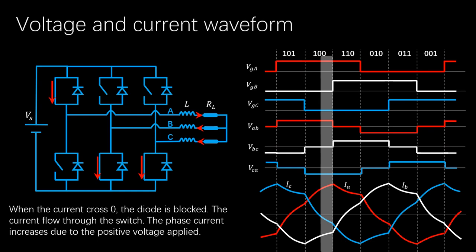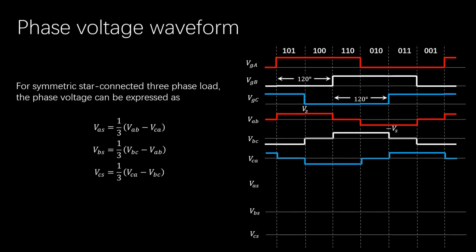In the view of small time scale, it absorbs the energy from the DC side, and at the same time, it also feeds the energy into the DC side. There is bidirectional energy flow. However, in the view of large time scale, the energy flows from the DC side to the AC side, realizing the inverter function.